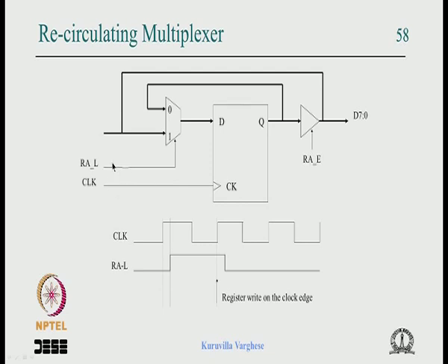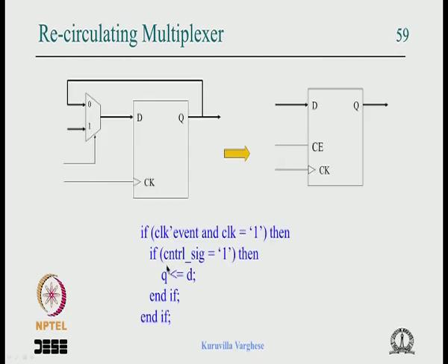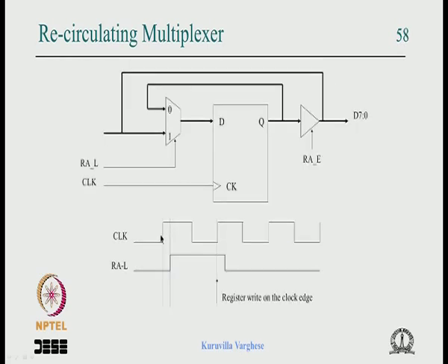Since the latch signal is coming from the state machine, there will be a delay with respect to the clock, the TCQ plus TCOM delay, and you can see that this enable signal will come offset to the clock period.